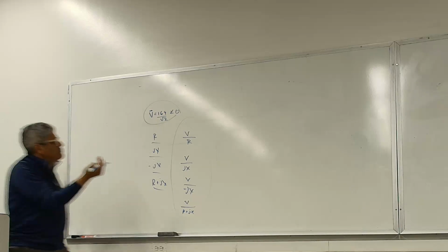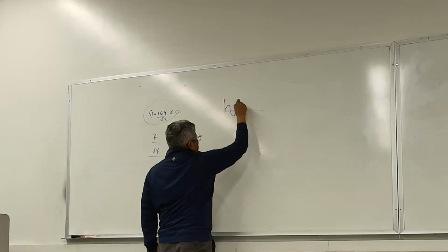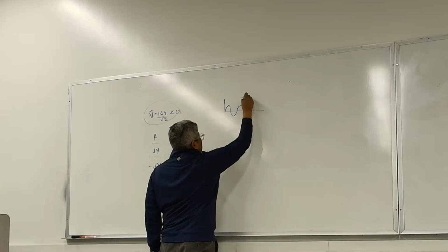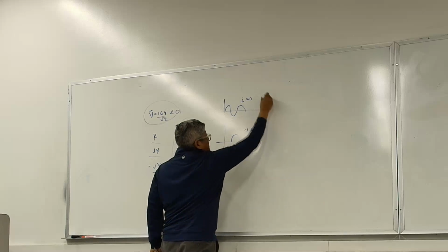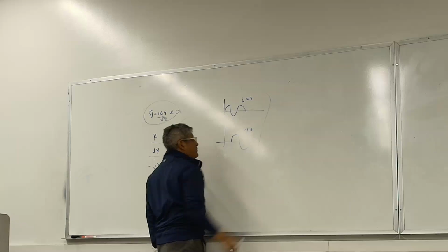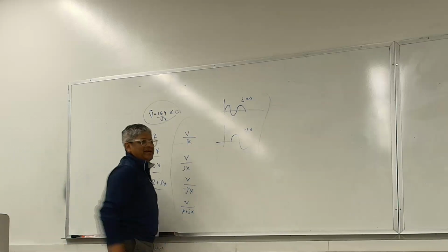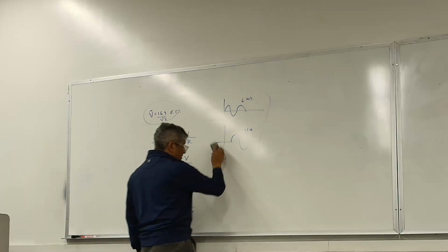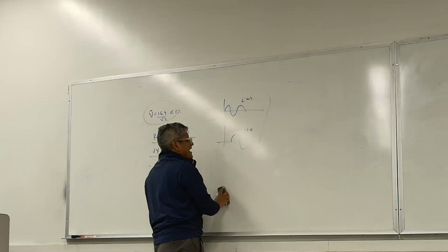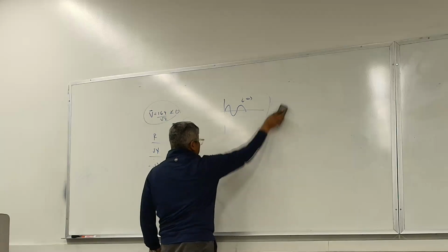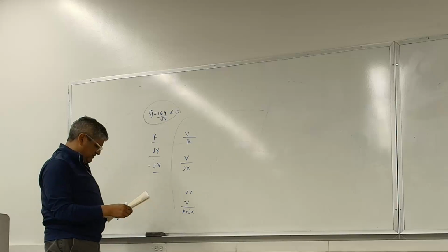I did have a couple of people, not a big deal, but again, I asked for the phasors and they were giving me this, I of t and V of t. And they explained this should be in phase, this should be 90 degrees, but that's not the phasor diagram. This is time domain. And remember I said that, right? Usually we don't give this as an answer in this type of problem. We want the phasors of it. Let me see, what else did I notice on this one?